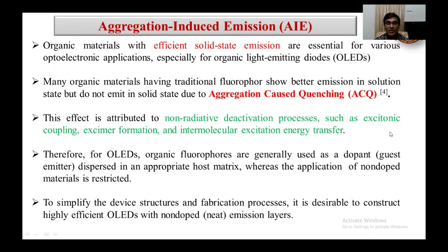That's why for organic light emitting diodes, the organic fluorophores, the emissive molecules, are generally used as a dopant, that is the guest emitter, dispersed in an appropriate host matrix, whereas the application of non-doped material is restricted. But to simplify the device structure and fabrication process, it is desired to construct highly efficient OLEDs with non-doped emission layers.